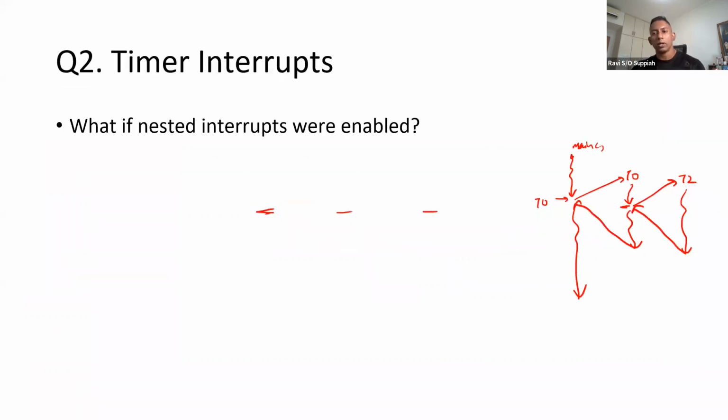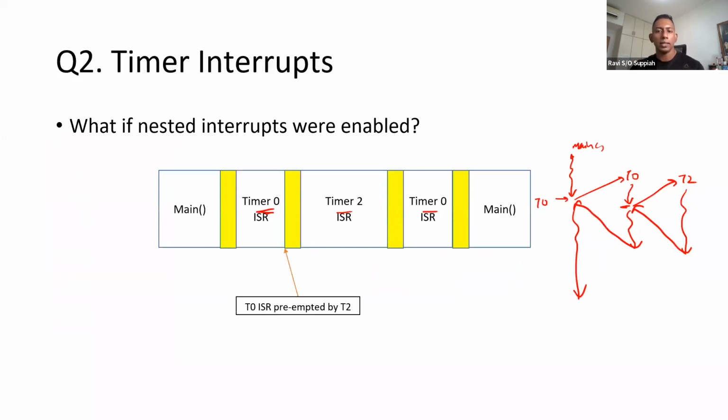The important thing you must understand is that the hardware module is designed so that the interrupt is there and the PWM or CTC pin generation is also there, but they are both separate. They can be mutually exclusive. You don't need one for the other.